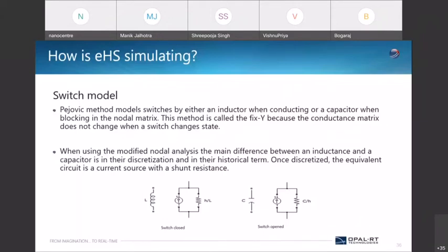Also, MATLAB has its own solution: if we open any power electronics converter, any semiconductor block from the Simulink library, we can make the semiconductor switch operate in different modes. One is called switching devices, one is called switching function, and one is called average controller. These are ways to suit whatever the user is interested in.